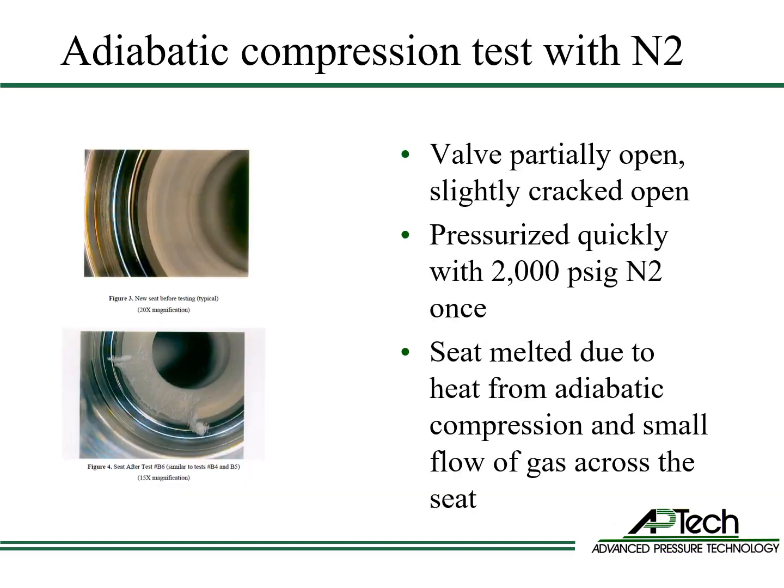While the classic adiabatic compression failure is oxygen and residual oils, even inert gases and polymers can experience adiabatic compression failures. In this test, a valve is partially opened and pressurized quickly one time with 2000 psi of nitrogen. The PCTFE valve seat melted due to the heat from compression and the small flow of gas across the seat.